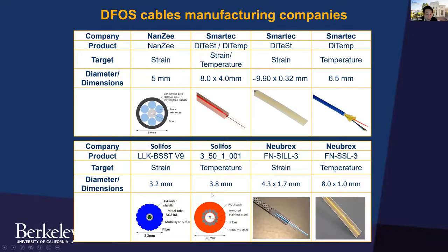You can also have a temperature measurement. In that particular case, when you step on it, you don't want to have a strain transfer. But if this fiber is floating inside the gel, then the change in temperature will be reflected over here. Meaning that the strain cable has 2 components, which is often the case, strain and temperature. So you need to have one cable to do temperature compensation to get your strain, as for typical sensors that are temperature sensitive.